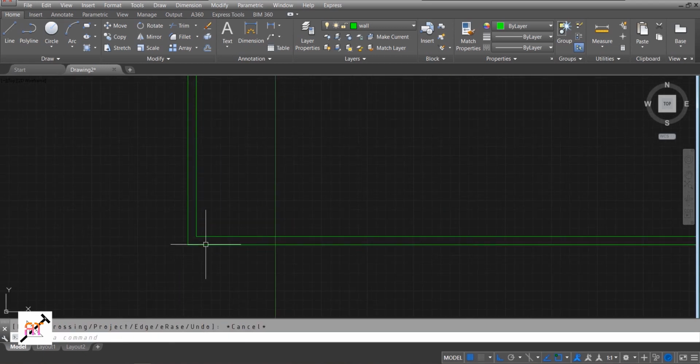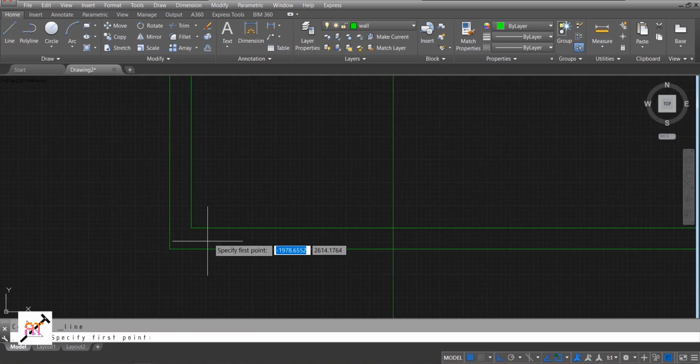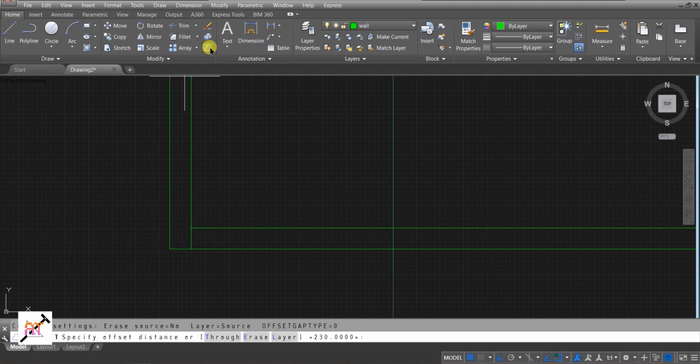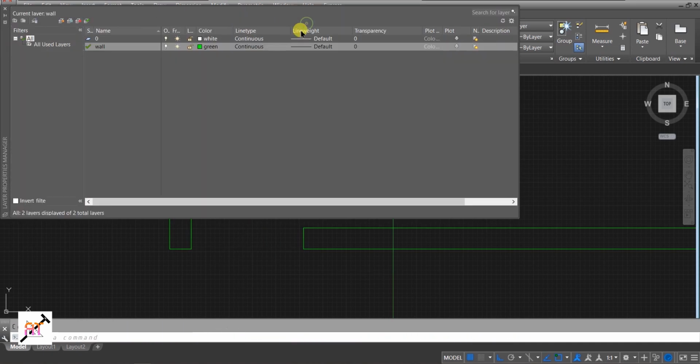Now let's cut walls for adding doors. We'll add 1.2 meters door as main entrance. First we will draw a line, joining corner of inner boundary to outer boundary. Now let's give offset of 1200 mm. Use Trim tool to trim the lines in between. Let's add the door.